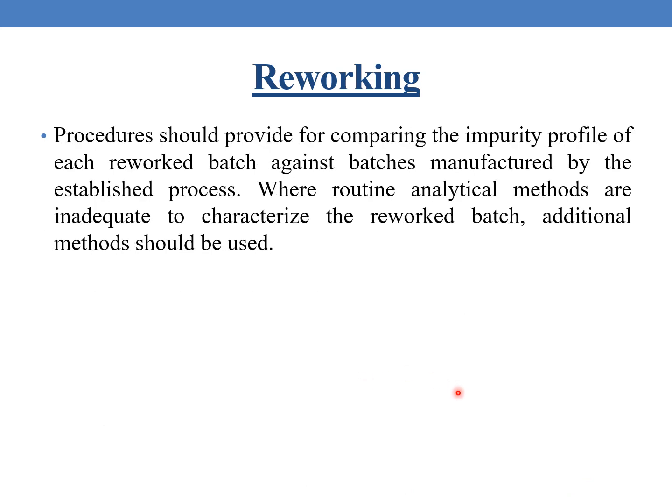Procedures should provide for comparing the impurity profile of each reworked batch against the batches manufactured by the established process. Where routine analytical methods are inadequate to characterize the reworked batch, additional methods should be used.